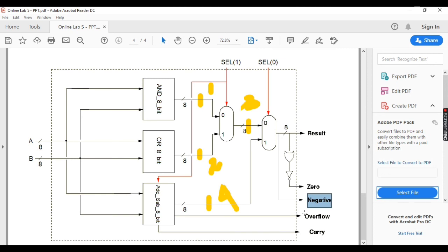That is why we are not designing our ALU using the behavioral way. But as we have mentioned, while designing any hardware circuit, we design it both in the structural way and in the behavioral way, because it helps to verify the functionality of our design. It's the convention to design the hardware in both ways. If we design it in a structural way, we can design each and every module on our own, and our final top level module will be as optimized as we wished it to be.